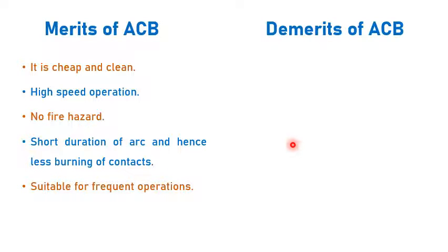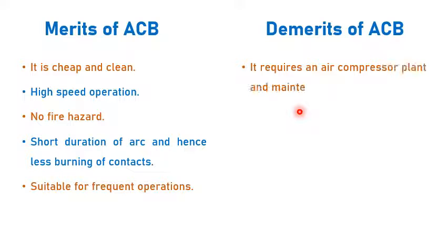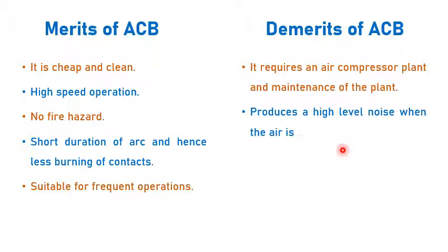And similarly there will be demerits. It requires an air compressor plant, especially for storing the compressed air, and obviously that requires maintenance also. It produces a high level of noise when the air is discharged. Whenever the circuit breaker opens, the air blast passes across the arc with heavy sound.